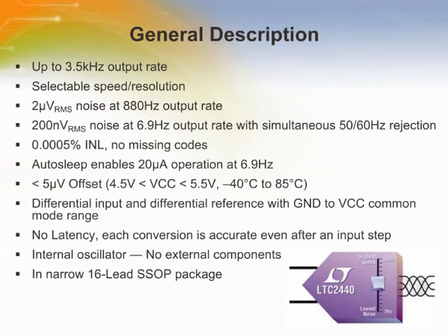Following each conversion cycle, the LTC2440 automatically enters a low-power sleep state. Power dissipation may be reduced by increasing the duration of this sleep state. The LTC2440 communicates through a flexible 3-wire or 4-wire digital interface.